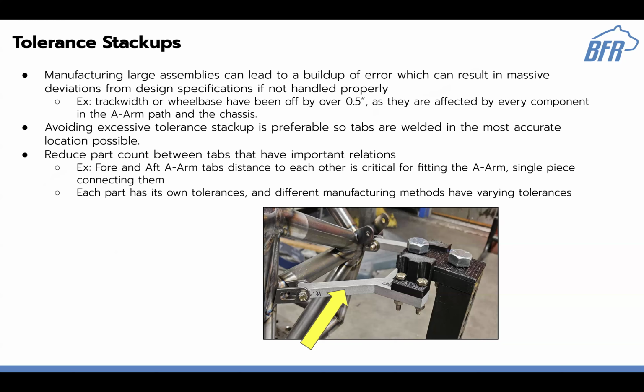I know some people have said Baja welds their chassis in-house, and sometimes their dimensions might be off, like total length. I think sometimes might be up to like an inch, right? Which sometimes you can accept, right? But in certain cases, for a lot of suspension geometry, you might want it to be a bit more accurate. Obviously, since we're using VR3, which is a professional weld shop, they can get a lot closer tolerances than us, which is really nice when we're doing our design. Theirs is closer to like 60 thou off for relative tube placement.